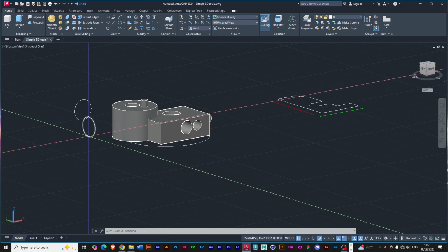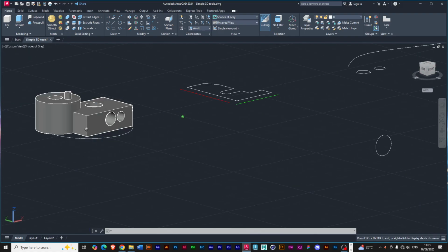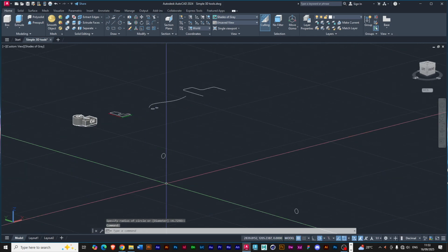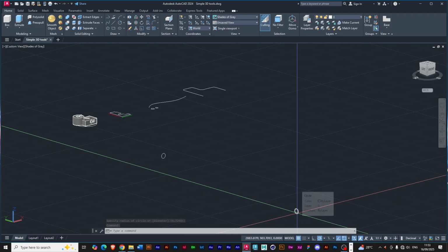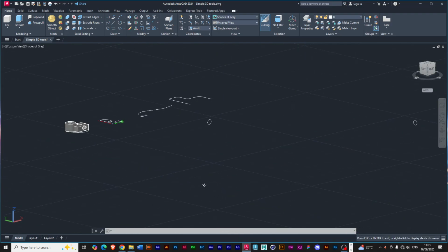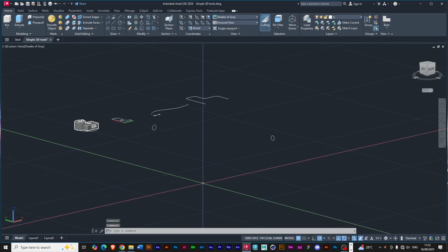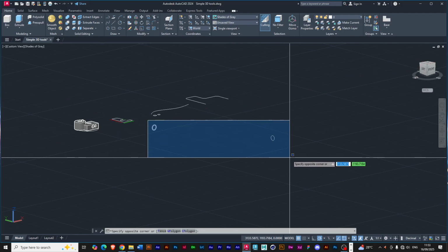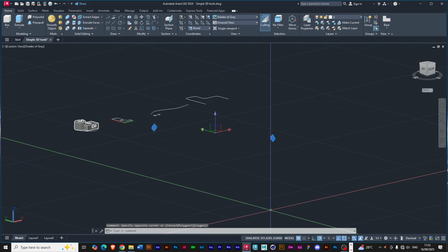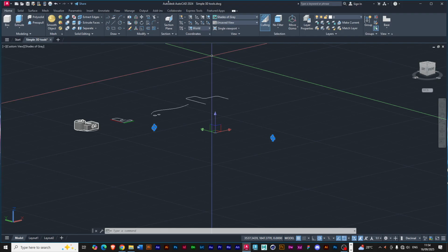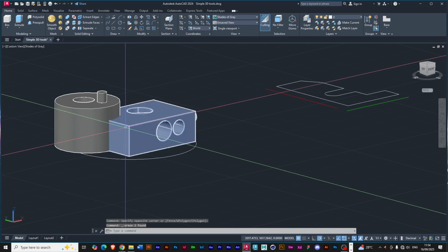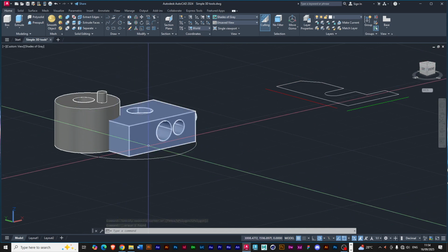But now you have two circles facing in weird positions. This is the first one. This is where the second one has gone to now. So that is what those planes are. To be smarter at work, we prefer to use the dynamic UCS, because when you do things like this, it will just throw your shapes to places that you don't understand where they went. Okay. All right, so that is for press pull and extrude.